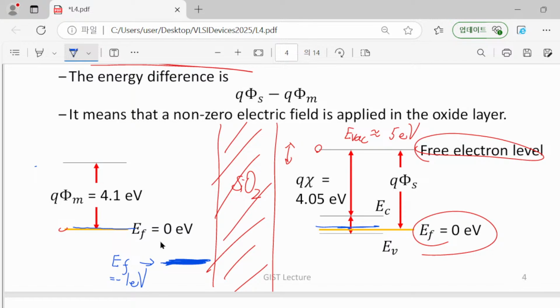So our device is actively providing our charge carriers into this p-n junction system in order to eliminate this Fermi level difference. However, in this MOS system, due to the existence of silicon dioxide, even though we have energy difference, Fermi level difference, there is no current conduction.